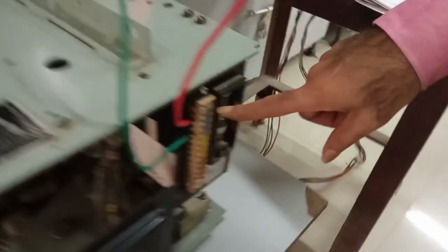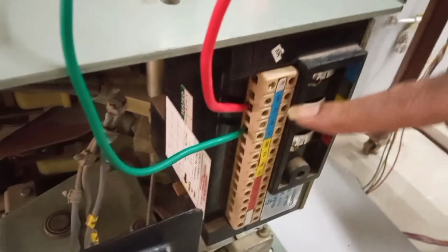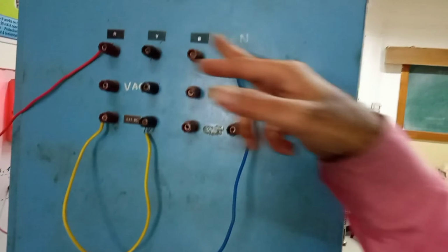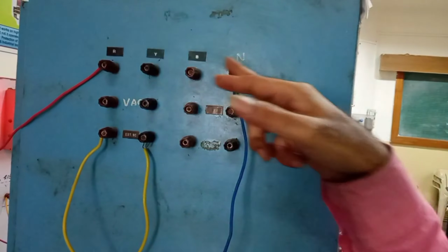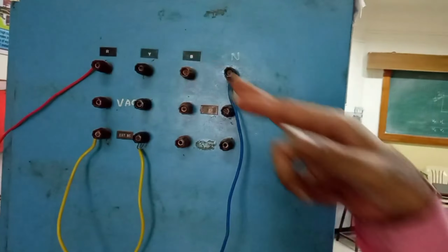Right. Then these two terminals, T1 and T2, I have connected to the current source, red and green wire, through which I am going to inject the current. Between T1 and T2 the thermal bimetals are there in the circuit, and these red and blue wires are coming from the under voltage release, which are connected to fixed 240 volt supply. So now presently the breaker is in a closed condition, right?